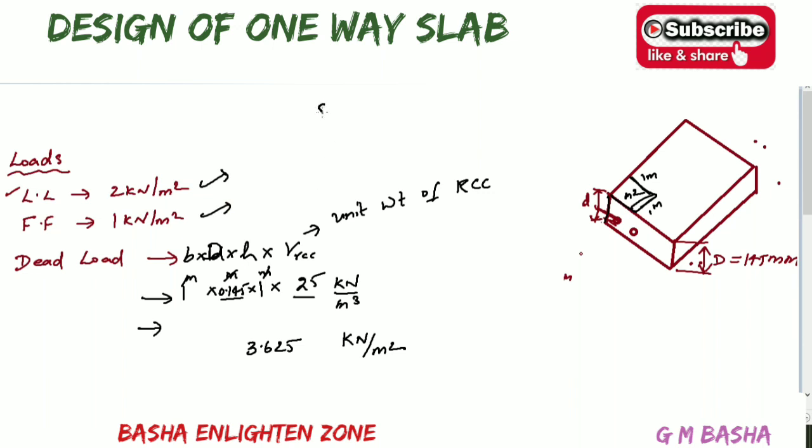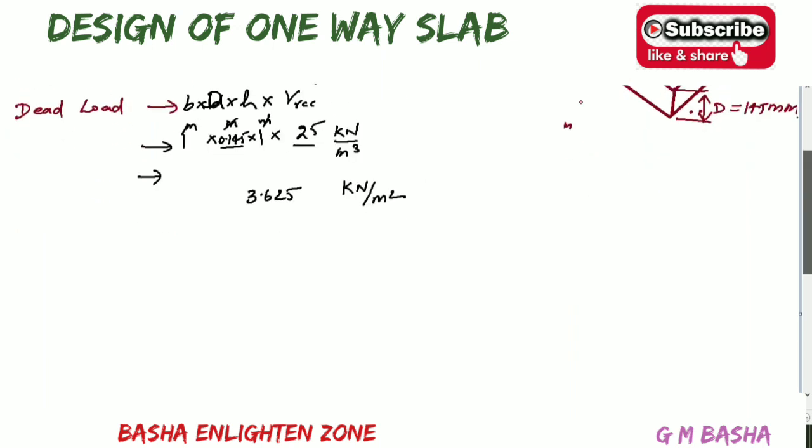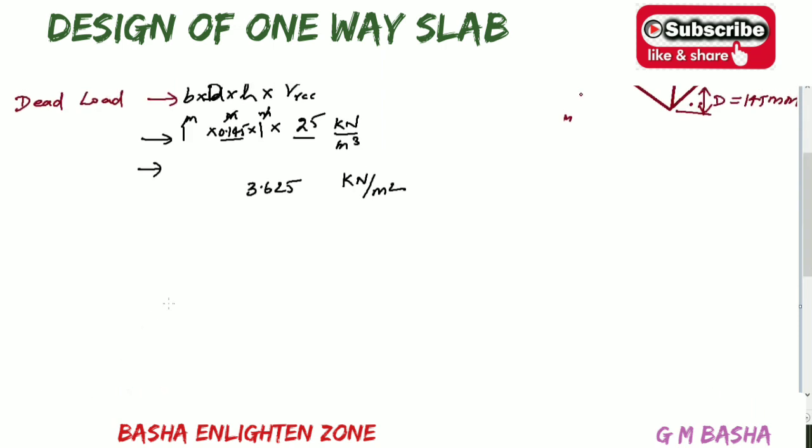For example, if you see the same thing for the beams, I will explain beams here. So dead load for beams will be taken as B into D into, again here also H into the unit weight of RCC. You will get that in kilonewton per meter only. Why? Because here the beam will be like this.